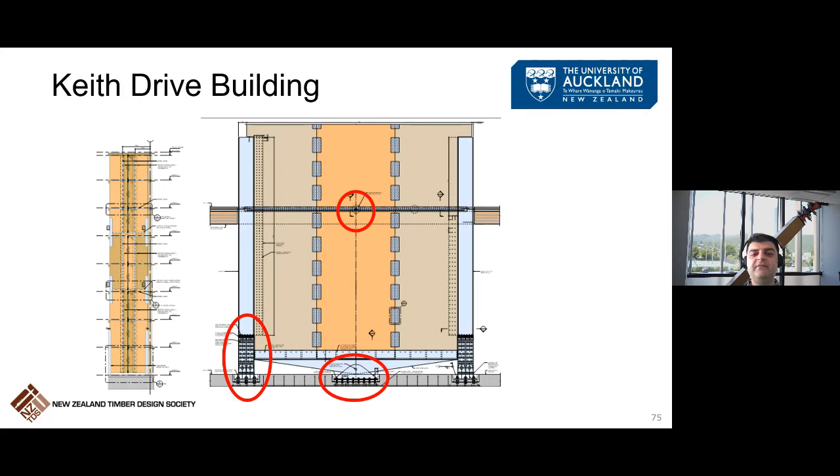As a secondary mechanism, they had yielding perforated plates between the segments, so it was not a single wall. During large events, RSFJs will activate, and then as a secondary mechanism, these will yield, giving a robust system.